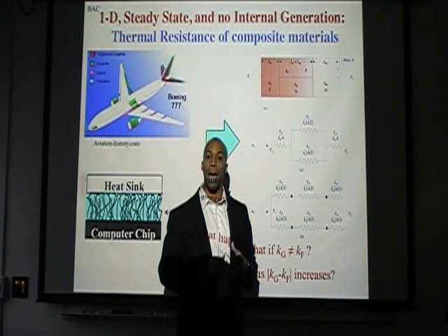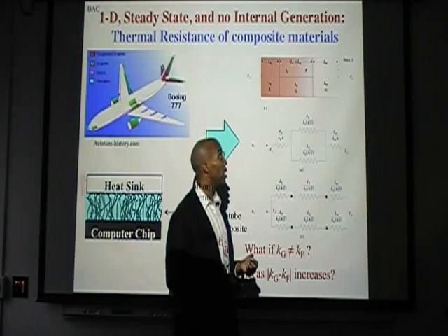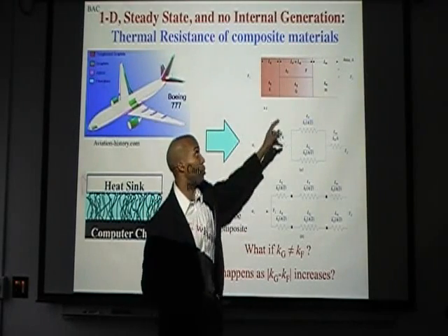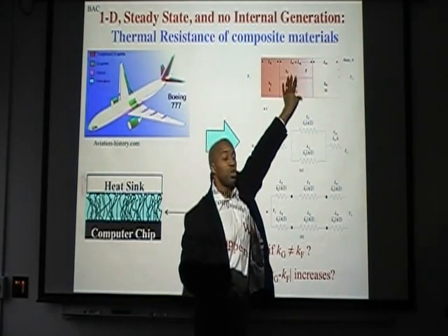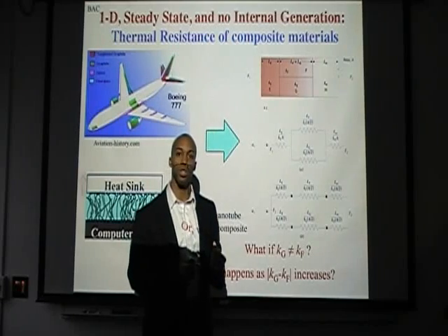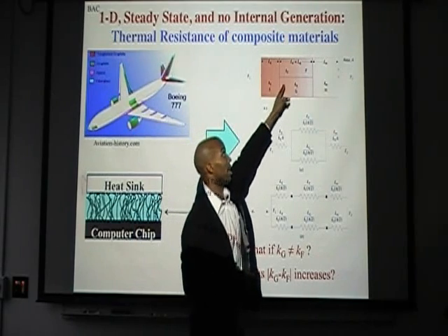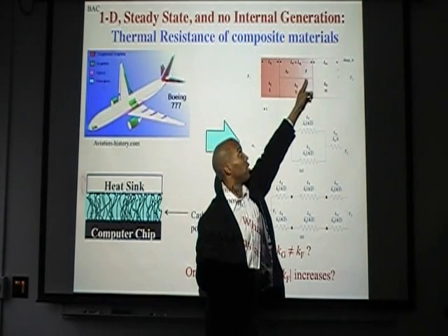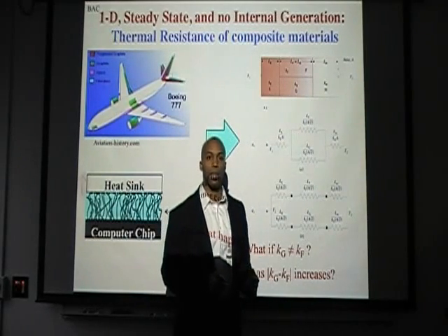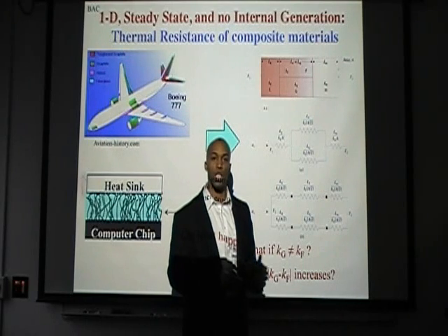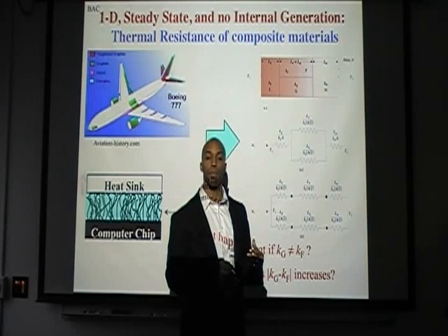So it's possible, when this thermal conductivity difference is great, for two-dimensional heat flow effects to show up in a problem like this. Meaning that the line between the two materials would no longer be adiabatic, and it's possible to have heat flow across that line.